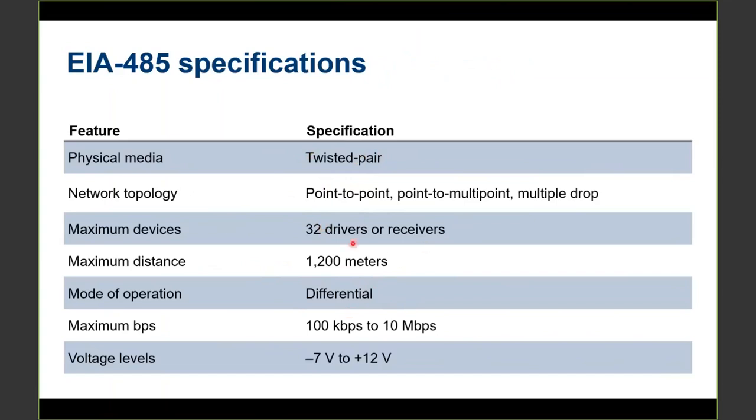The maximum number of devices you can have on a 485 circuit is 32. Chances are you probably won't run into that theoretical maximum; the most I usually see is maybe 8, 9, or 10 devices on a string. But you have to consider that if you have a client or master device, let's say an RTAC, talking to 6 relays that are all multi-drop with 485, and you want to pull information from each relay sharing the same comm channel, you need to poll the first relay, get the response back, then poll the second relay, get the response back, in a round-robin fashion.